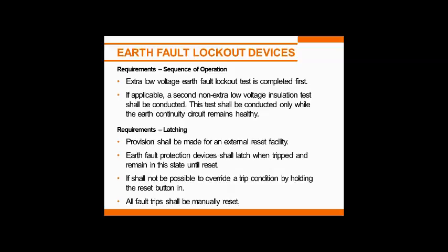Now the standard also allows for a second high voltage output. Some of our more complicated relays, like IPMs or IPCs, integrated protection relays, will, after the first low voltage test, put out a high voltage test and do an insulation test of the cables. With the cheaper relays, that's considered not required, and it would also increase the price dramatically. And so it's not done in the cheaper single function relays.